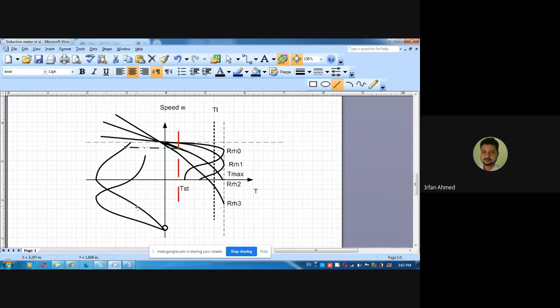When did I say that? I did not say that. I asked whether you will disconnect the supply and connect a rheostat across the stator terminals, and whether that will give dynamic braking. I did not tell you; don't put things on me. I also told you that that will not give you dynamic braking. The motor will simply stop, like it stops when you disconnect the supply.